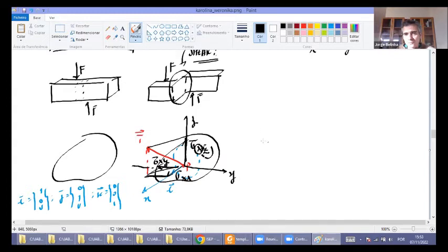You understand this? So from this, T is equal to this vector plus this vector plus this vector. See that all of them start with the x, on the x direction, y and z. If it is normal, it has the letter sigma. If it is a shear, it has the letter tau, and the other two letters in the index are different. Understand?